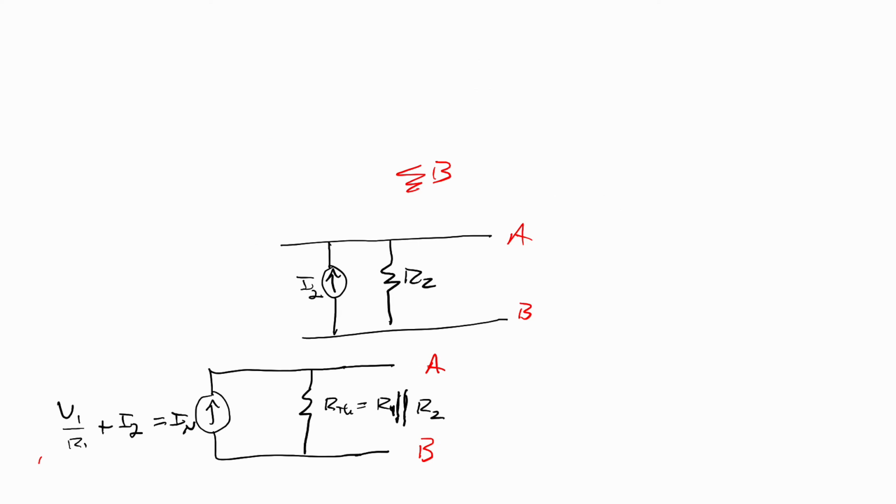So we can use Thevenin and Norton, that system of opening up and shorting sources to find the resistance, as a way to simplify a more complicated circuit. So obviously just a Thevenin source by itself is maybe too trivial.